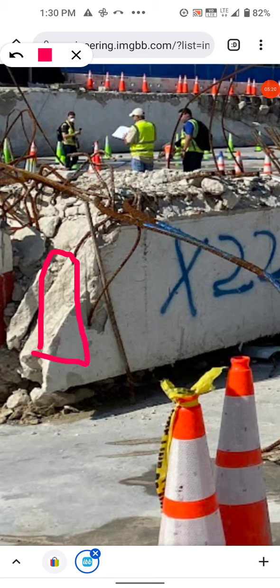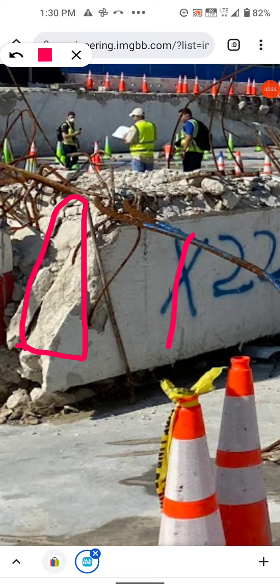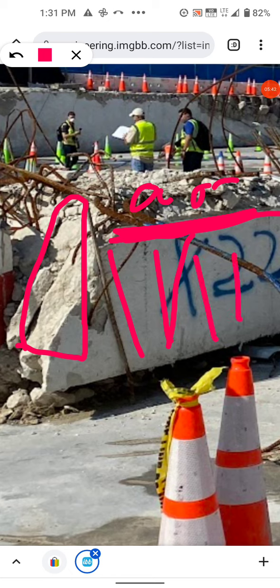Not quite. They don't stop there. So the stirrups go here, and they go up above that, above this plane right here. See the plane of it? They go above that. In fact, you're looking at the stirrup locations. So if you look at this, you can then reverse engineer this beam. You see the stirrups. You can see how much they put up top there.